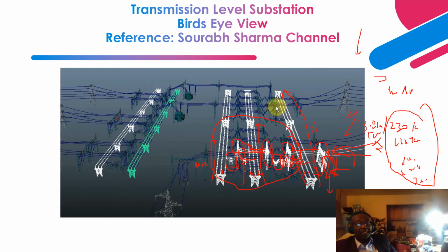So it allows you to energize power from here to here, from here to here, and energize these buses in between based on the switching function that you have. From here we have risers, conductors that get integrated to the first main bus to energize this bus.